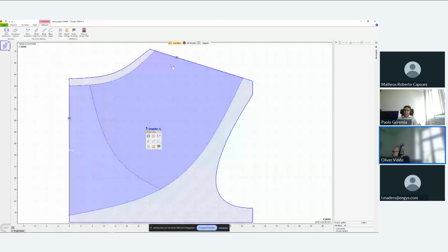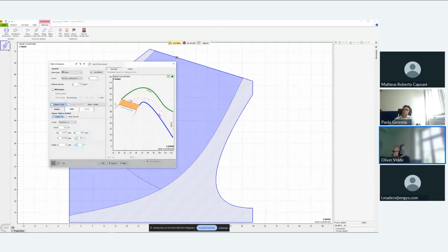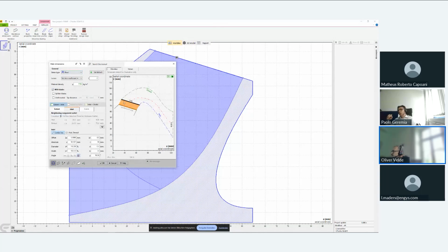I want to finish that stage design, and by doing so, I'm going to add a diffuser that should do two things. It should bring the flow back to the inlet diameter of the impeller, and it should reduce the swirl, in the best case down to 0. And to this end, I'm going to add a bowl diffuser type with blades, of course. Again, main dimensions will be the first step, so the location of the inlet hub and shroud point and the outlet hub and shroud point.